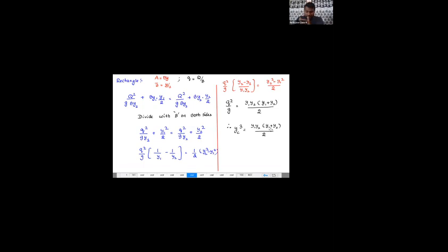See, don't blindly remember this equation. These relations are for the conjugate depths, not for the alternate depths. Now let's go back and check with the one condition. So I hope you understood this. Q square by g is equal to y1 y2 into (y1 plus y2) by 2.